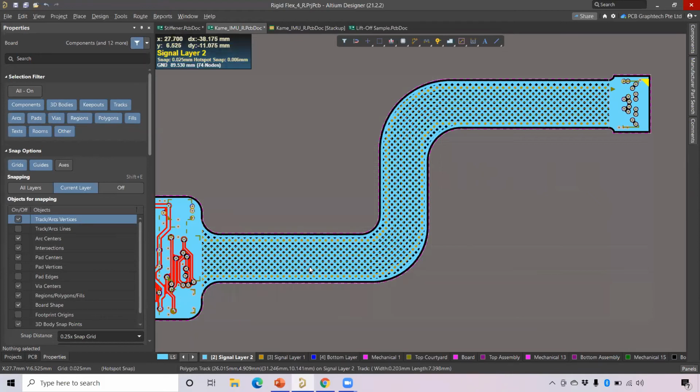For high-speed design, high-frequency circuits, there is a possibility for the high-speed trace. Okay, you have a high-speed trace means there will be a signal integrity issue. Because we have hatched pattern here with the angle of 45-degree, in the return path, the signal integrity will be degraded. Okay, so how to avoid that problem?